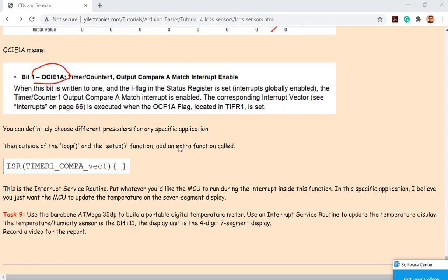Whenever you are displaying a number, the delay between every single digit needs to be even, so you can see a very smooth display. You do not want to plug the temperature sensing code in between the display scanning. So you need an interrupt to test the temperature and then come back to the display.